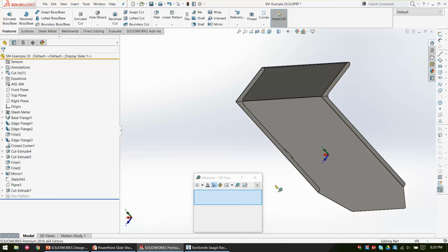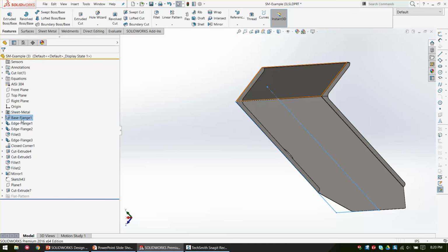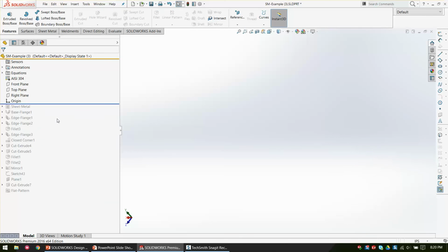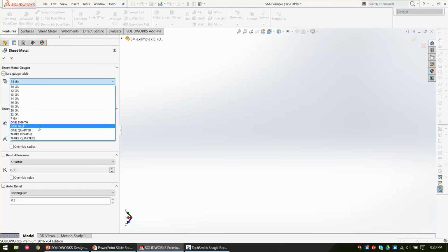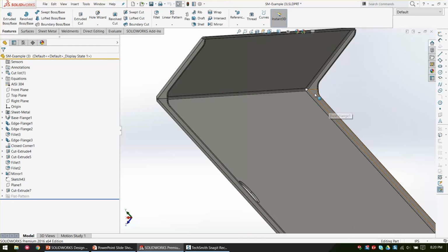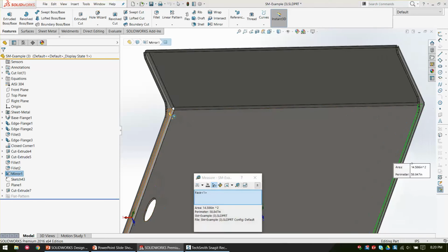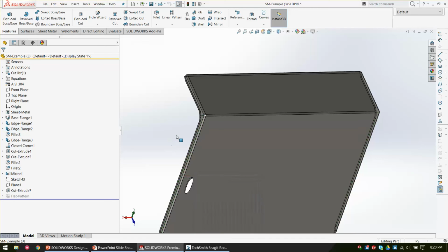So no matter what, and here's the design intent, I anticipate this material will change. Absolutely, I've changed it multiple times already. So if I change this material from 18 gauge to 1/4 to be ridiculous, what's my inside dimension still going to be? 34.25. Because I added material to the outside, no matter what the material does, and I anticipate the material to change, my core critical dimension stays consistent.